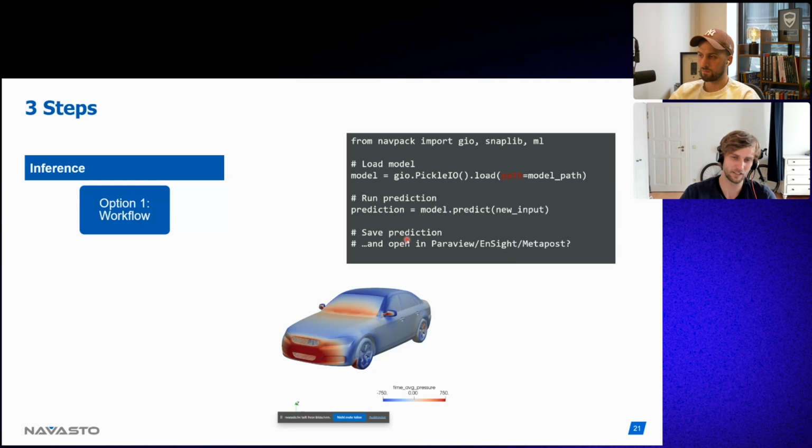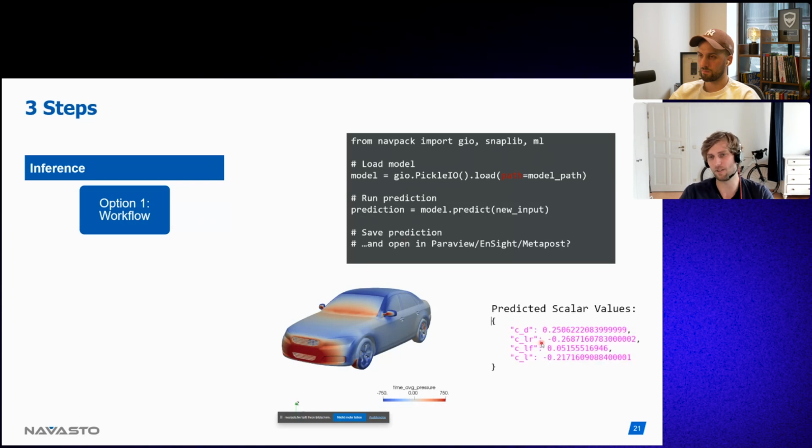It's quite nice because if you use a GNN, you really have a 3D object. So you can rotate it, clip it, make some cuts. You are completely free to apply threshold filters, iso-contour filters, whatever you want. But you can also create automated pictures like this, or visualize the predicted drag values. So you get predictions at the end for everything you put into the training.